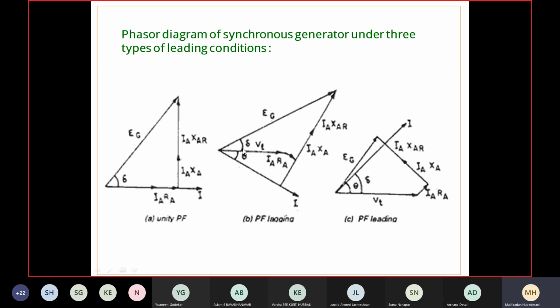This plays a vital role in the transfer of power from bus 1 to bus 2. That is what is called the power angle study of a synchronous generator connected to a bus when delivering power. This angle has to be as narrow as possible, and we have seen the maximum when it is like that. So therefore this is for the lagging case.